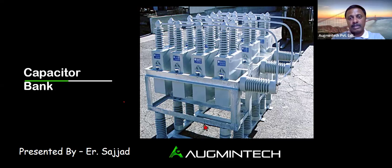So in order to overcome all these problems, what we have to do is install the capacitor banks, which are going to compensate for that reactive power. Again, I'm telling you, this reactive power cannot be ignored. It cannot be controlled at all. It would be existing. We can't do anything about it, but still we would be able to compensate. For example, 20 kVAR, if that's the reactive power.